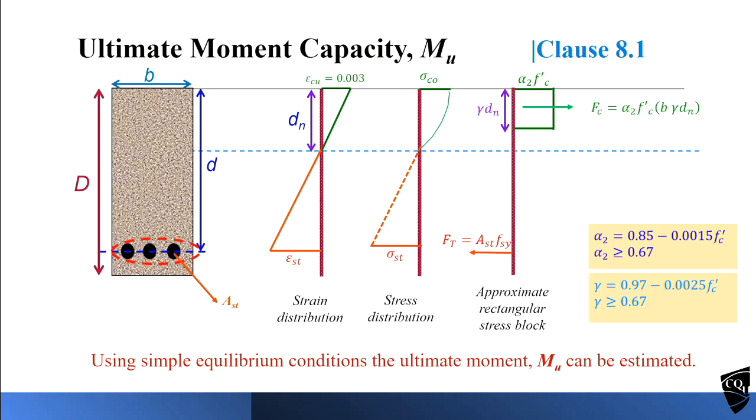So last week we calculated two depths of the neutral axis. One is for the cracked section, another one is for the uncracked section. So that is completely different. Don't confuse. That is the depth of the neutral axis for elastic materials. In that one, the concrete is assumed to be an elastic material under service load. This is under ultimate load. The load is much higher, so it is not within the elastic limit, so we cannot use any of the theories we learned last week.